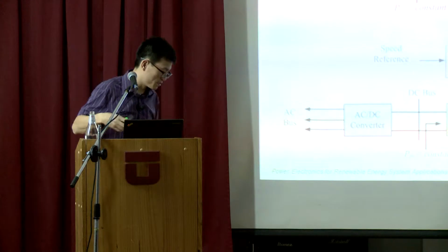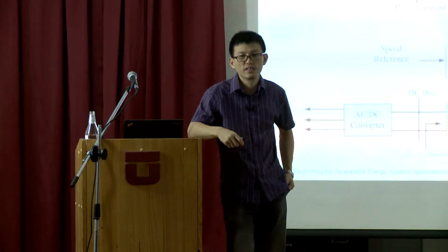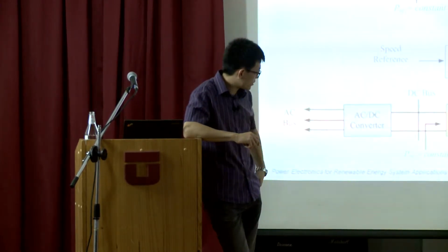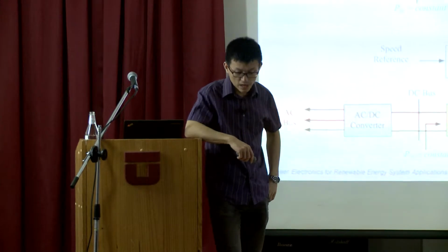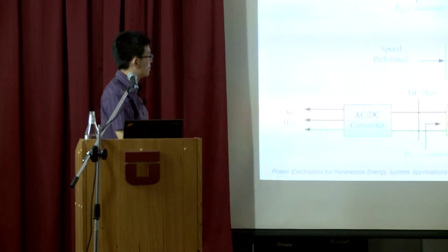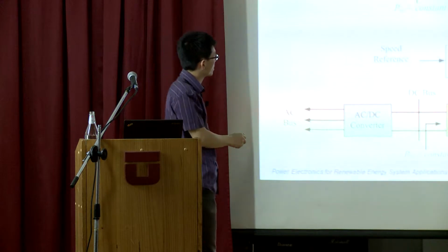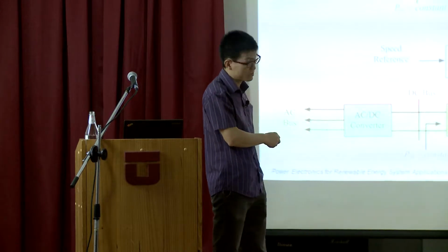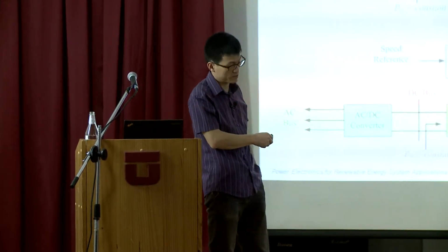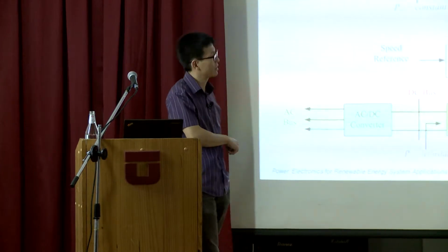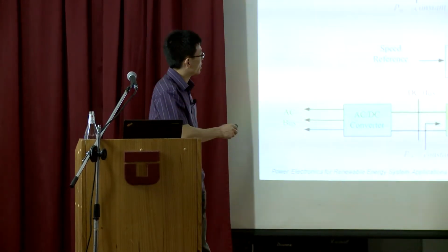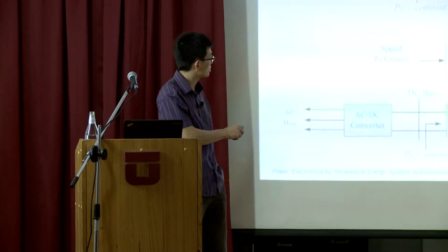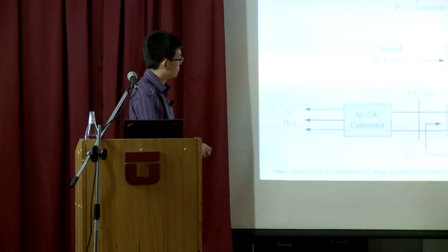Everybody knows this constant power load is always a big problem for the electrical system. In electric aircraft, or in general, there are two main types of constant power loads. One is the DC converter. Essentially, what's happening is the DC converter controls the voltage here well. So in that case, if you have a resistive load, the power here is constant, which means the power here is constant. This is why we call it constant power load, because the power at this point is constant to the load.